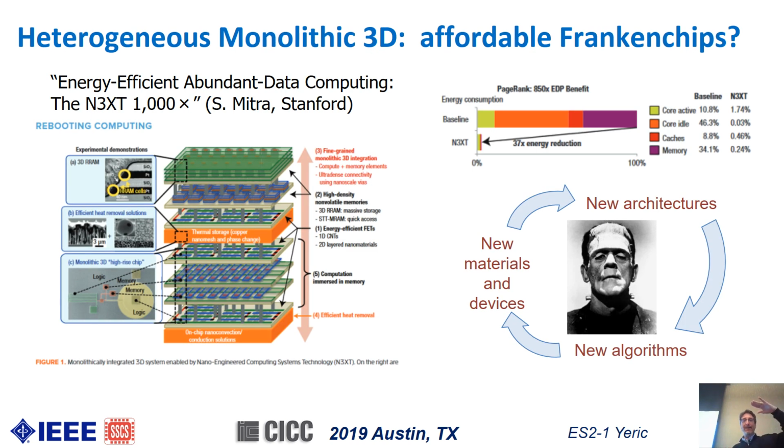Now, that was a discussion about plain CMOS CPUs. But the really exciting stuff is if you can put wafers together, they don't necessarily have to be the same type of wafer, right? You could put a CMOS underneath an RRAM, underneath carbon nanotubes. And what I'm discussing actually is this paper from Stanford, where in addition to heterogeneously stacking different things, they're using it in a machine learning architecture that specifically is designed to take advantage of the high-level interconnect density.